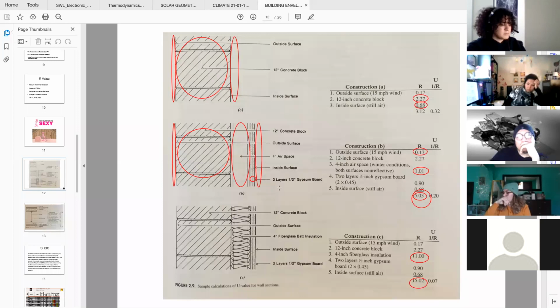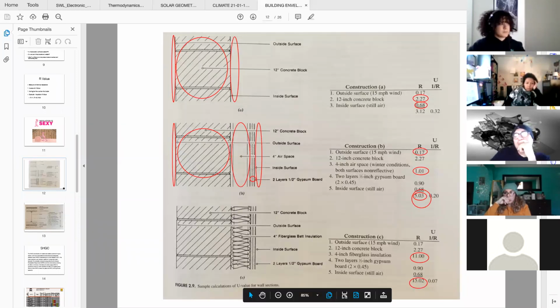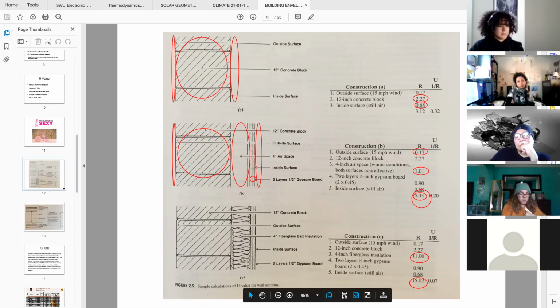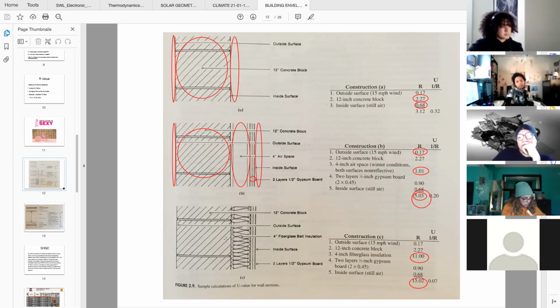And again, the reason air is the number one insulating material, and the reason the batt insulation is creating such a high performance, is it's adding a lot of surface area and very small air volumes, so the air is hitting all of those surface areas and not going straight through one giant airspace.